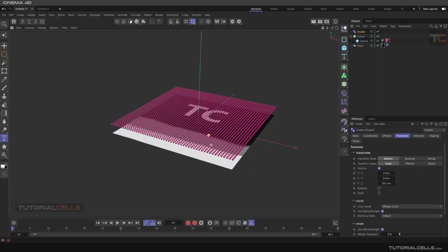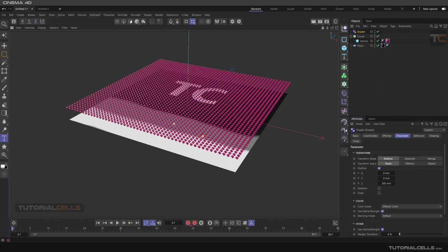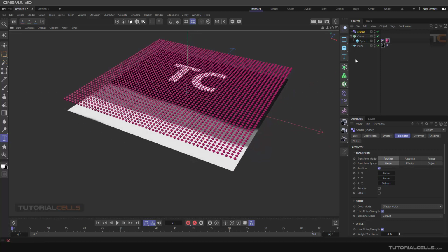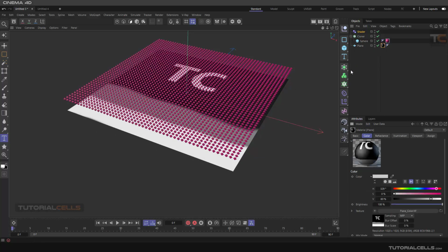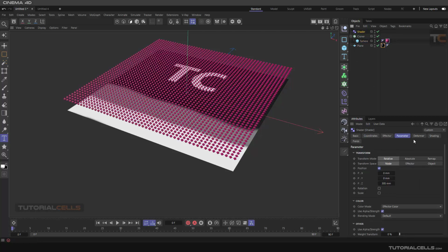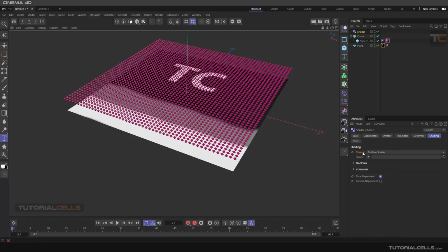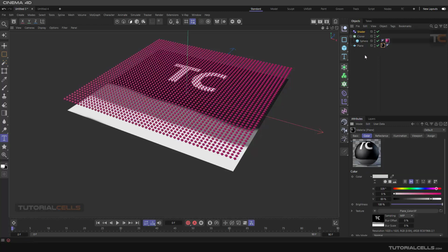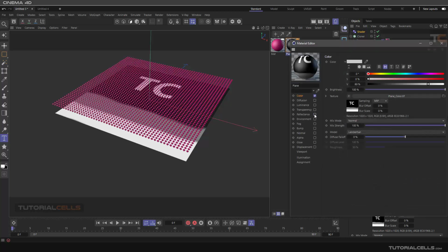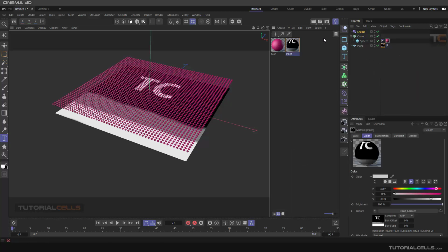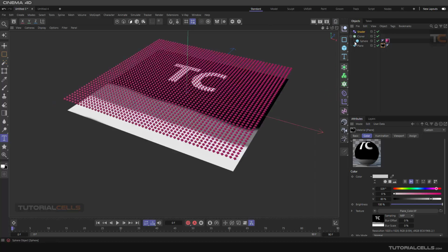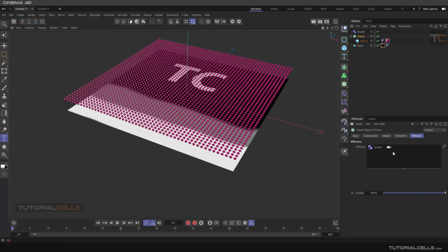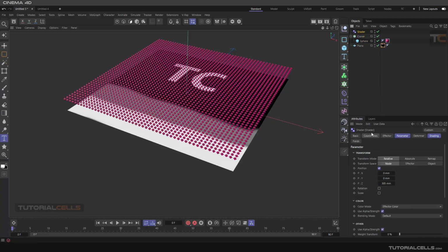And as you can see, it's completely bringing up all of the objects of the cloner. But we want to use a shader. As you can see, this is our texture that creates our texture on it automatically. So in a shader, we have to go to the shading, and a channel is very important. In a channel, you have to set it to color because it is exactly in a color mode of that. You can go here, double click, and change the reflectance to make the specular disappear.